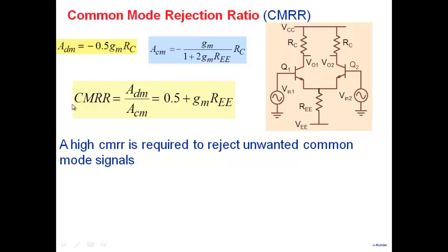I have the freedom to choose the resistor here, and note that once you choose the value of the resistor here, the current gets fixed. Supply voltage will be fixed by an application, let's say plus 12, minus 12, or plus 5, minus 5. So once the supply voltage is fixed, the moment you make a choice of REE, given the minus 0.7 here under bias point analysis, the current becomes fixed.